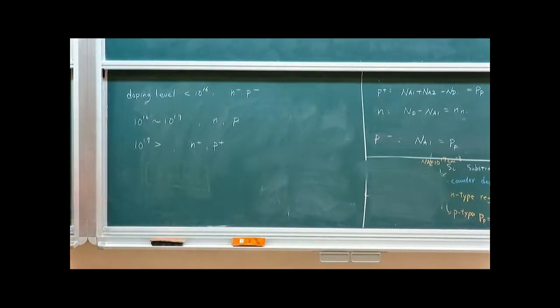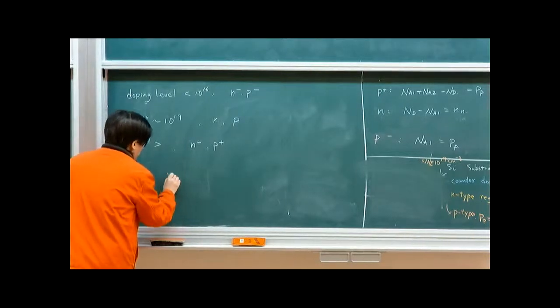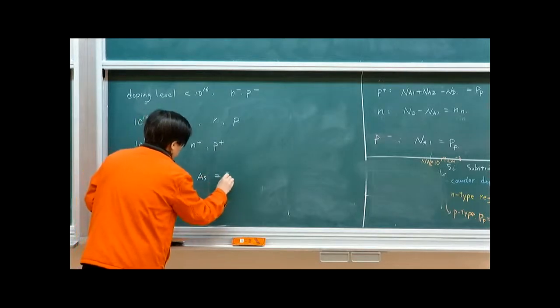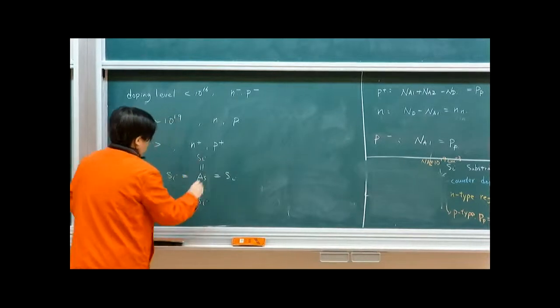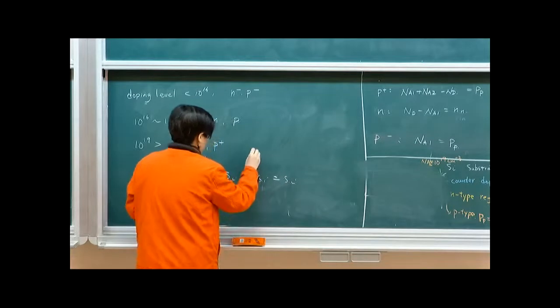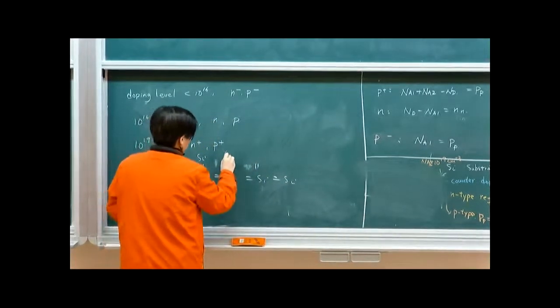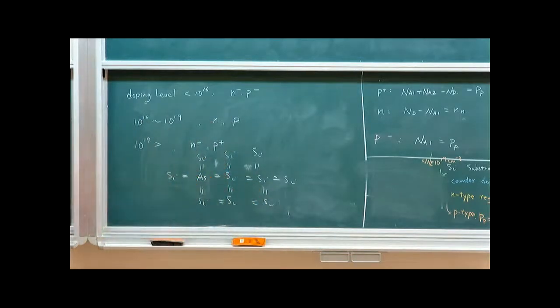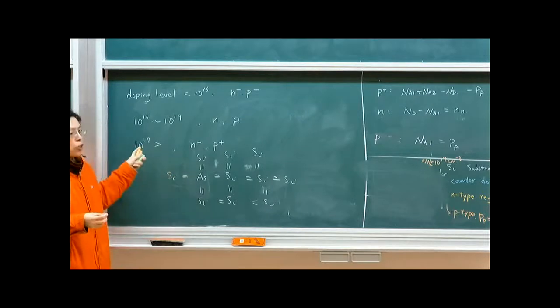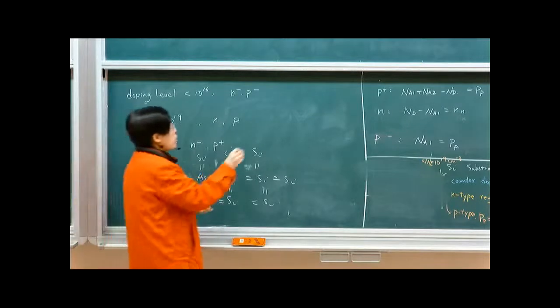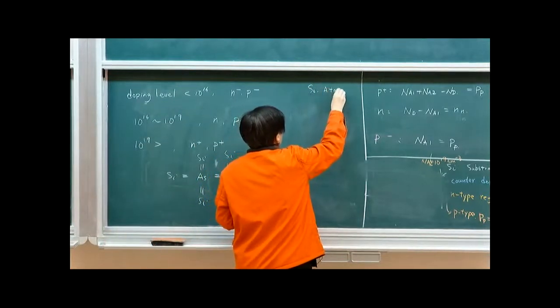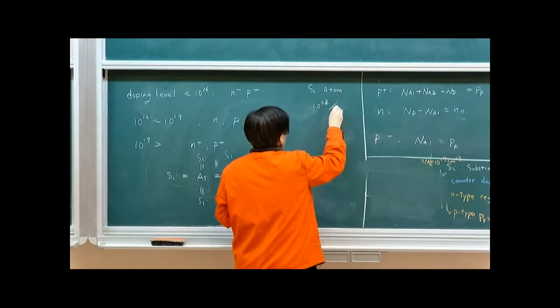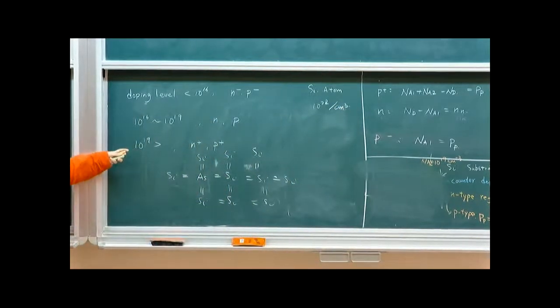The other thing I want to mention is that whatever doping you put into the system, there are very, very few dopants. If I'm simply drawing a figure like this, let's say arsenic, what is to the right is all silicon. I just don't want to spend too much time drawing this. The point is that this is very, very rare. Even in heavily doped material, remember the silicon atom density is 10 to the 22 per cubic centimeter, meaning that if I'm doping with 10 to the 19th, you will only see 1 atom per 1,000. So this is very rare.